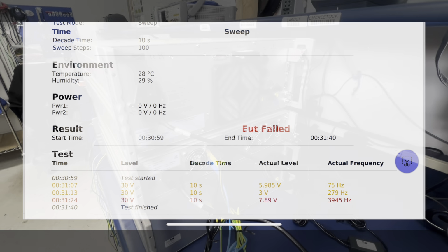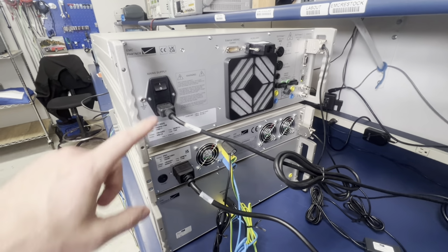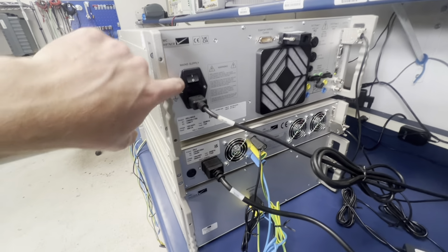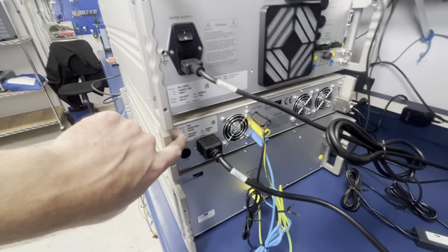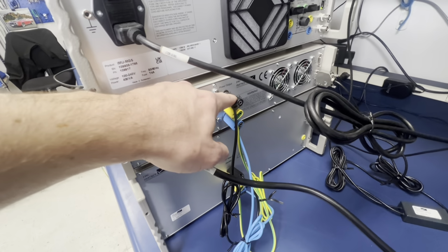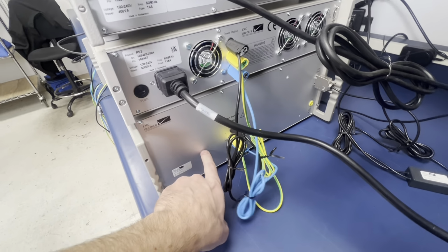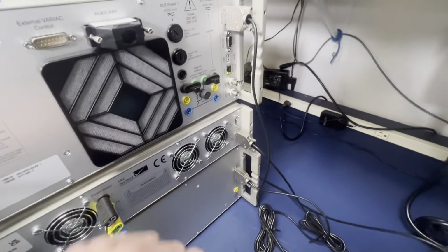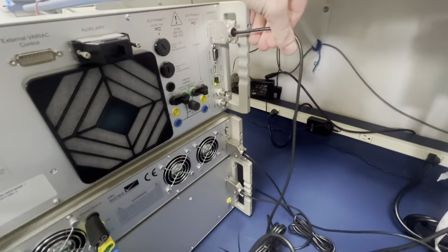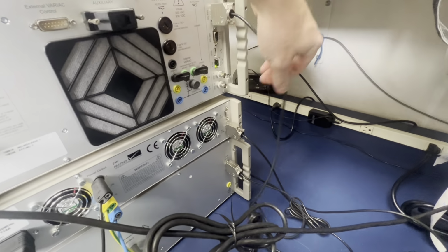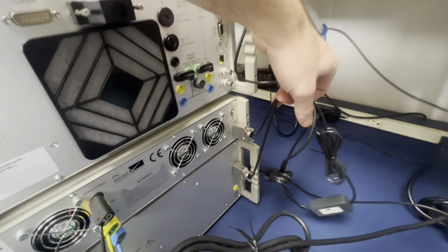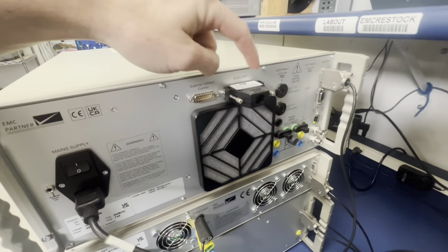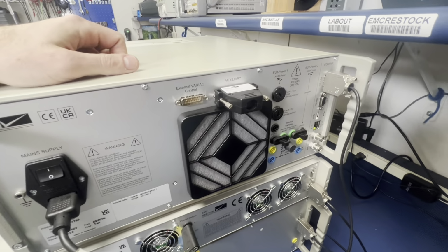And to quickly review the connections on the back, we have our power connections to these two units, the IMU MGS and the PS3. And the PS3 is powering the IMU C-short extension down here through these 3 banana connections. And then we have this nice comms cable RS485 to RS232 right here that connects all 3 units together for comms reasons, and then we have our safety circuit as well.